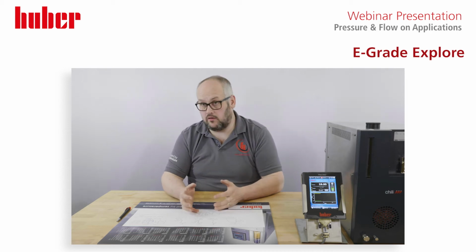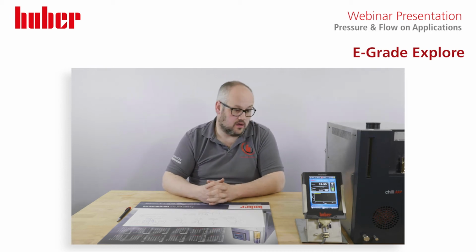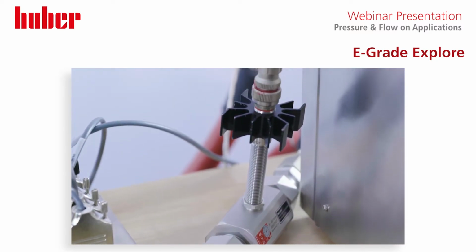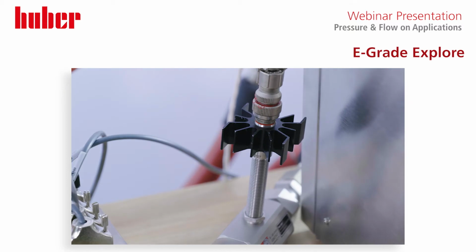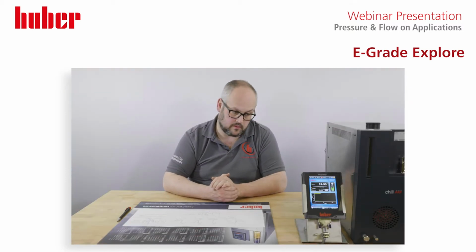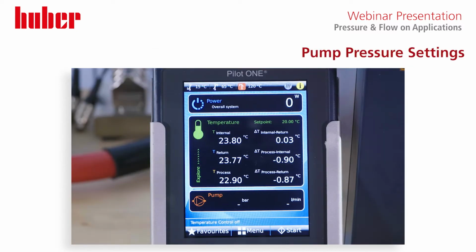Because we're using the silicone oil and because of our temperature range, I've chosen one of our turbine flow meters here. You can actually get ultrasonic flow meters as well, but for the little baby systems, I find the turbines are just perfectly fine. What does that all mean?